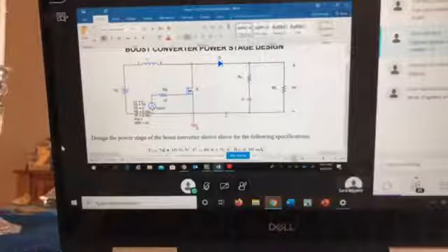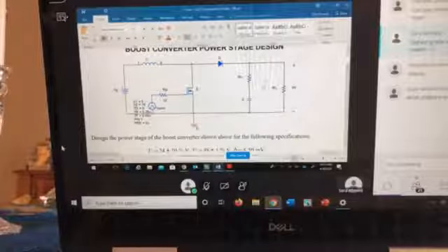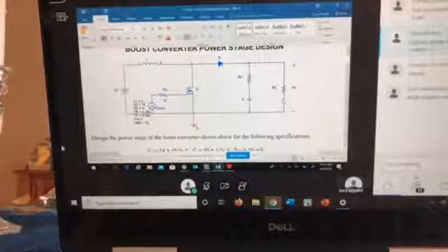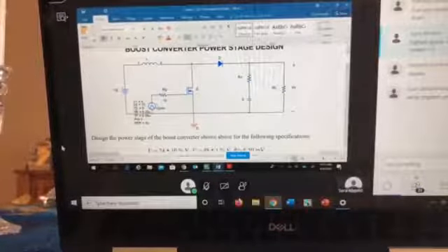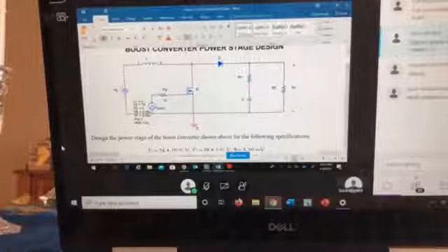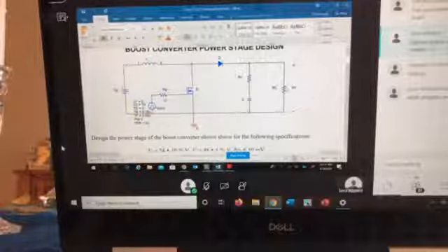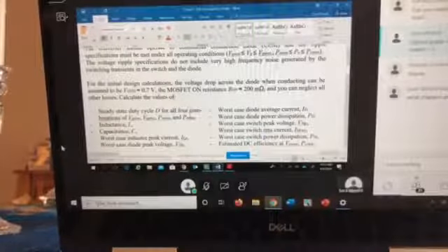So if you have a closed loop, whatever you're going to change in the load or in the input voltage, you have to still regulate your output voltage to a certain value. So how do you regulate that? It's by changing this duty cycle. And that's why you have 4 duty cycles when we do open loop. We're doing open loop, so there's no controller to make sure that this value stays at 48, right? But I'm gonna change my duty cycle to make sure that I stay at 48. Okay, so this is how this 4 combinations, which I think was confusing you guys, came from.